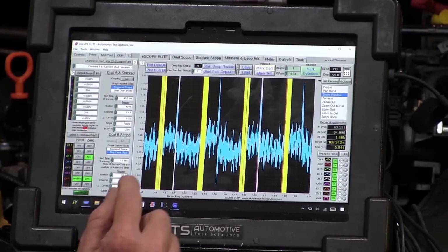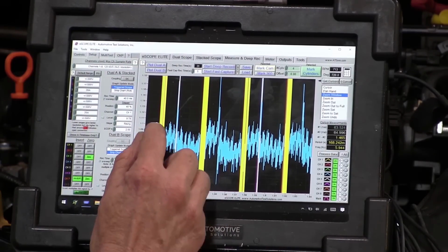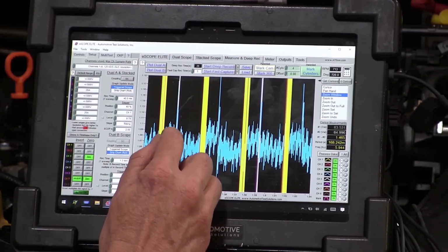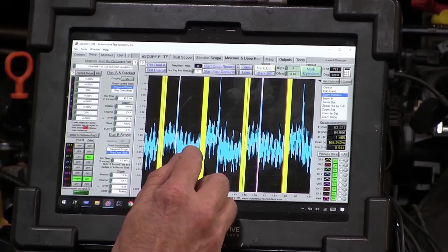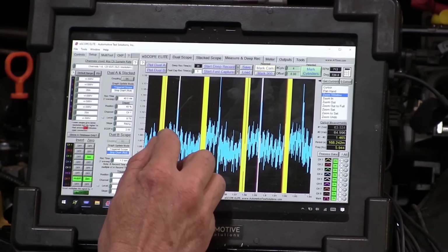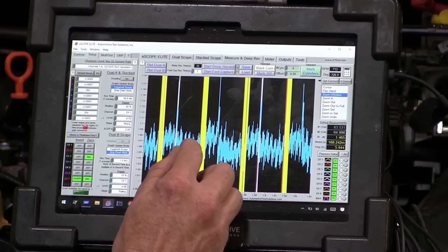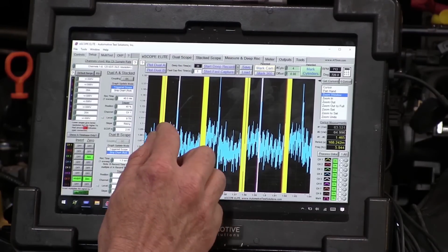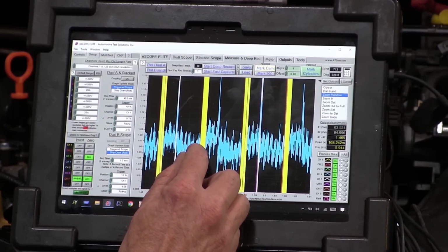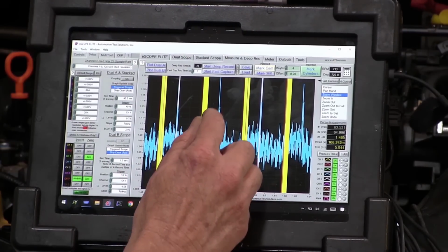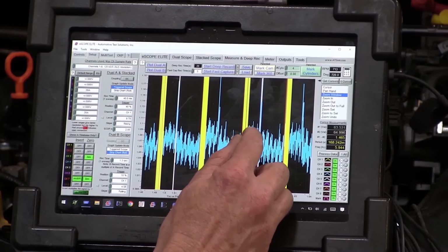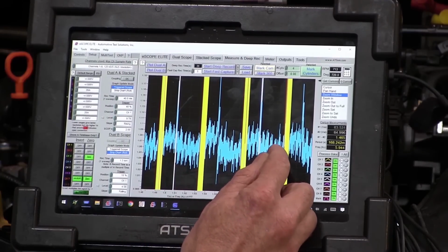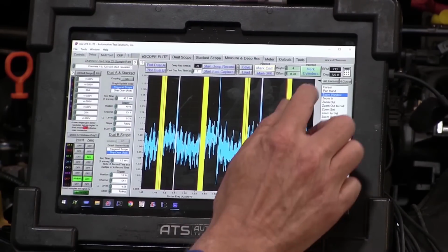Now what I want to show you is, do you see how I had a regulation event and I built pressure and then the injector turned on and I leaked the pressure off? Always remember, the injector is a leak. It's leaking the fuel off into the cylinder. I'm leaking the pressure out of the rail. I built pressure and then I had an injector and I leaked. Notice how they're all pretty similar.